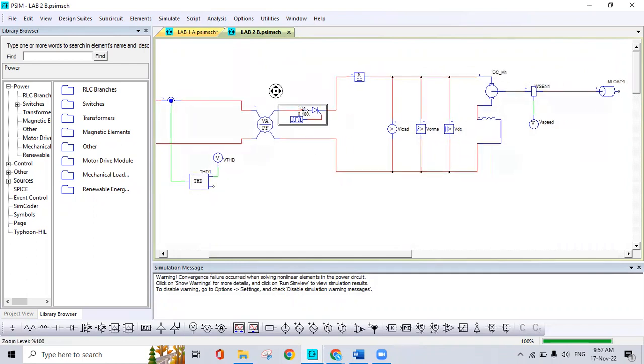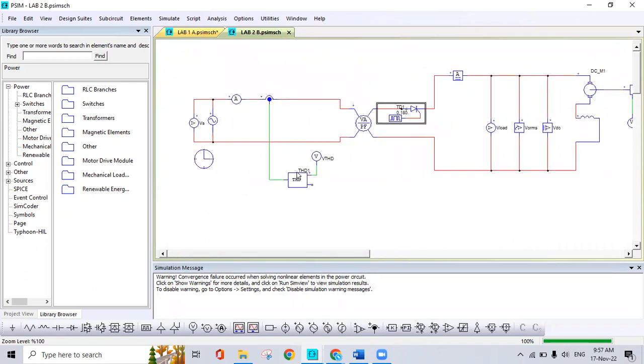Since we have an AC source as an input, the AC source will have a positive and a negative part. When it is the positive part, or positive region, or positive cycle, it will forward bias the SCR. When it is the negative cycle, it will reverse bias the SCR. So this is why, when we have only a single SCR, only the positive region or positive cycle of the signal can pass through or be output, but the negative cycle cannot.